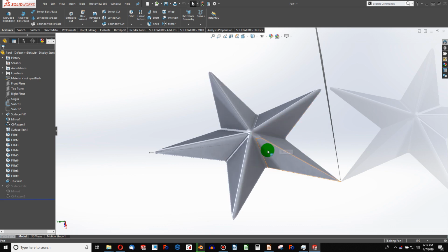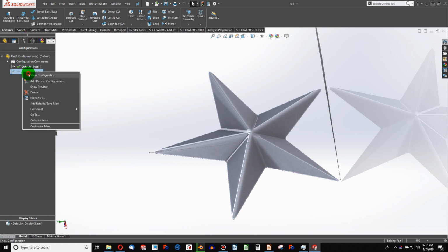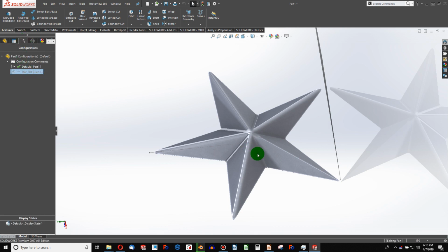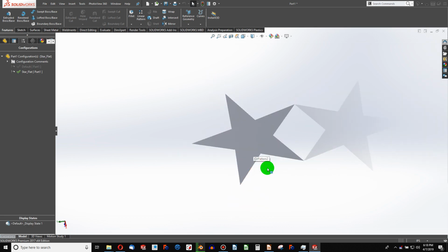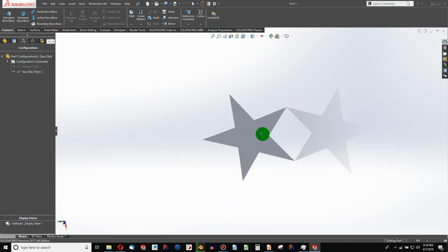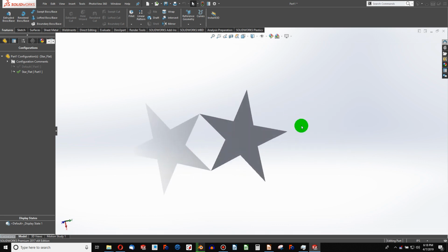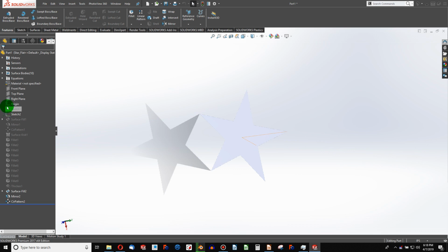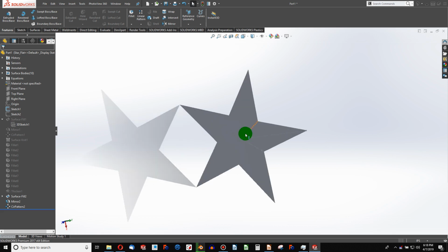So what can I do when I go and pick out my flat pattern? You can see my flat pattern may not completely update. That's because I need to reference the new dimensions off of that 3D sketch. So come over here, we'll choose surface fill. I don't need to have this feature unsuppressed, that would even mess things up, but I can unsuppress this sketch.